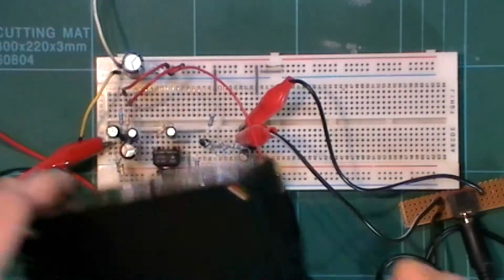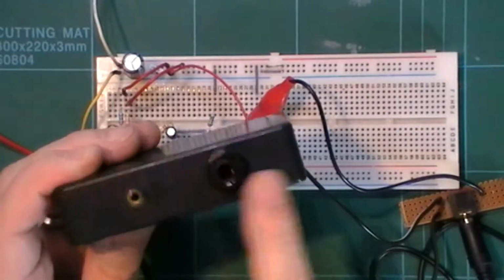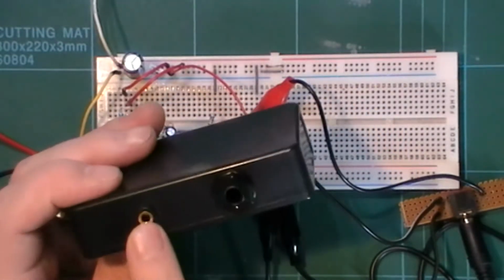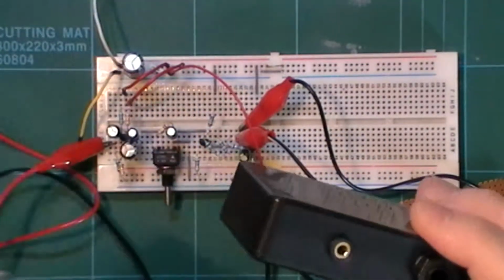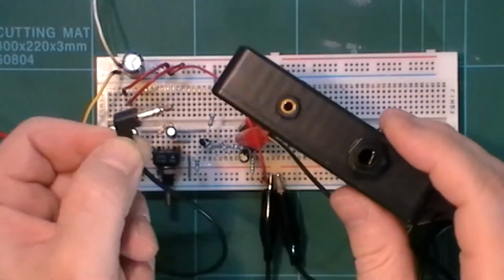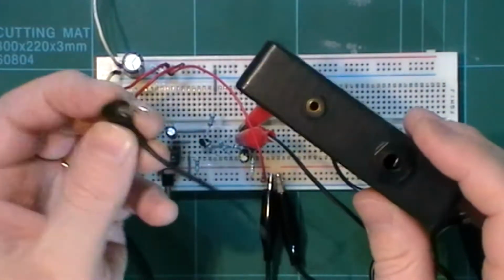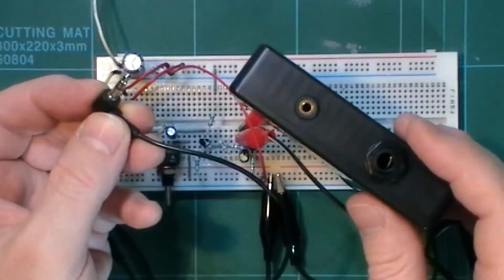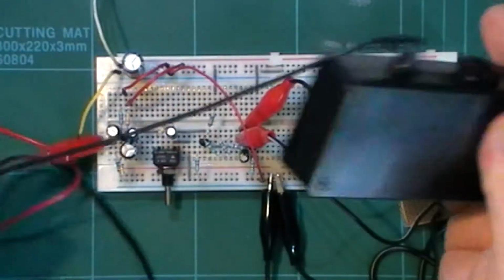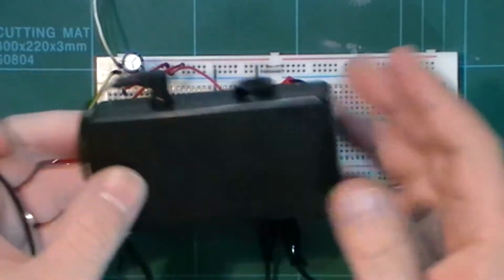With this thing, this is basically just an input, and it just comes off there. I split it onto the two connectors for the 3.5mm connector, which is tip, ring, earth, and that gives me my 2 channels out into my computer, rather than it just being mono, which is a bit pants, which has always been the problem.